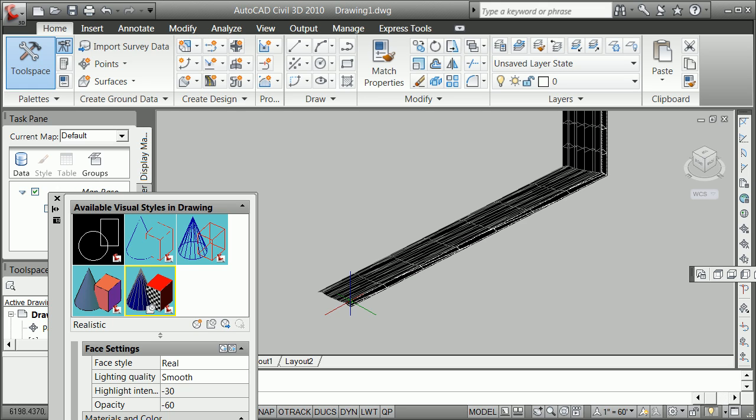And so as you start to try to take some of these skills that you have in Civil 3D and expand them out to a wider world, whether it be civil, whether it be architectural, whether it be conceptual, you have to start keeping track of what actually is going on in the program. And again, you're going to start realizing why these rules of keeping things in the right spot, either in your normal planar coordinate system like State Plane Central, or in the coordinate system that we define for profile information, station elevation times 10. You'll see why as you progress through the rest of the 2 semesters.